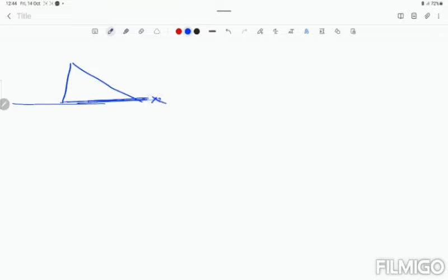This is our GL. If a certain amount of silt is deposited, then in the flow of the river, not only water flows but also silts and other things, and all that silt is deposited on the bed of the river. If you construct the dam, some amount of silt will be applied on the bottom of the dam. Silt also generates some force on the body of the dam at the upstream side.